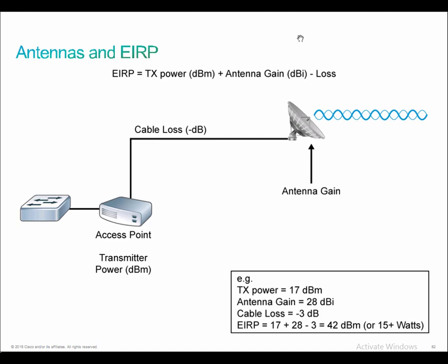The FCC determined that 36 dBm, or 4 watts, is the maximum transmit power. Now again, that's not necessarily applicable in an unlicensed band. That's in licensed bands as well. But it is important to know the effect of the antenna on your total EIRP, or transmit power. So you have to pick the appropriate antenna and the transmit power settings based on the regulations for the country or the region that you're in.